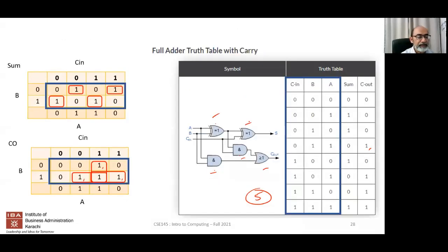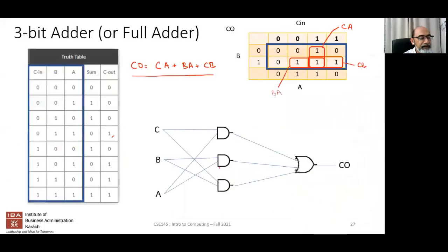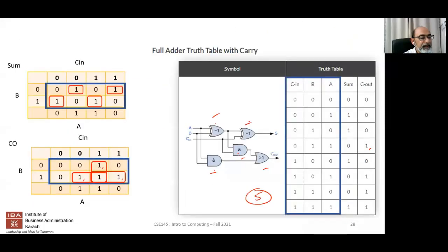So let's take a look as to whether this particular expression actually makes sense. If you look at the C out, that's fairly similar to what we had. We had an OR gate, and then we have two AND gates, and one of those AND gates is actually a combination of these. Basically, this is saying that C out over here is a combination of A and B. Let's take a look at S.